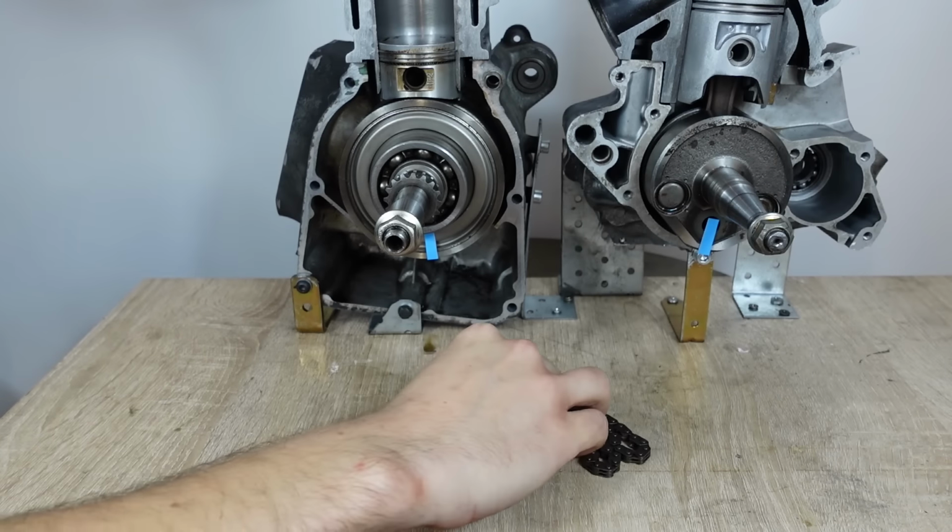Additionally, all of these mechanical parts are a source of potential engine failure. If they aren't installed correctly and the timing of the engine isn't correct, it can result in the engine running poorly. In extreme examples, the timing can be so off that it results in the piston contacting the valve on an interference engine. An interference engine is one where the valves and the piston occupy the same space but at different times. This can often enable a more compact, efficient, and powerful engine, but it also leads to engine failure in the event that the chain or belt snaps.